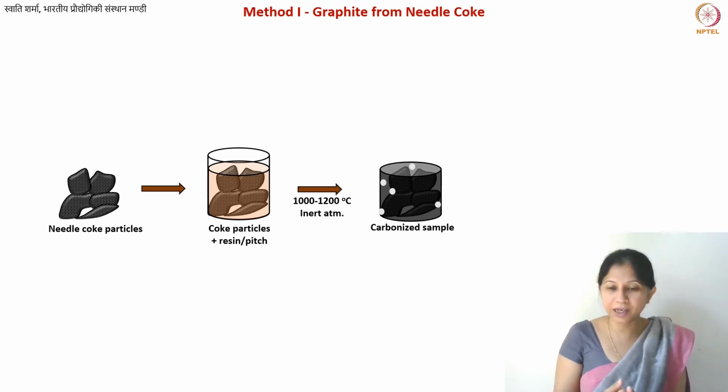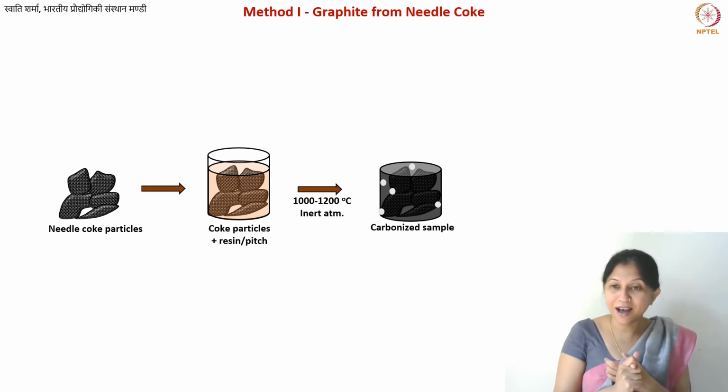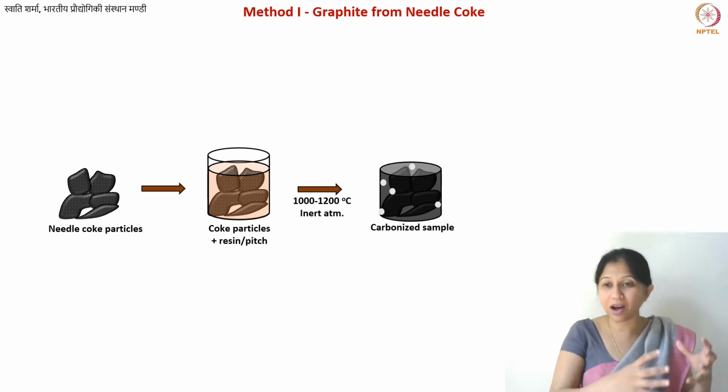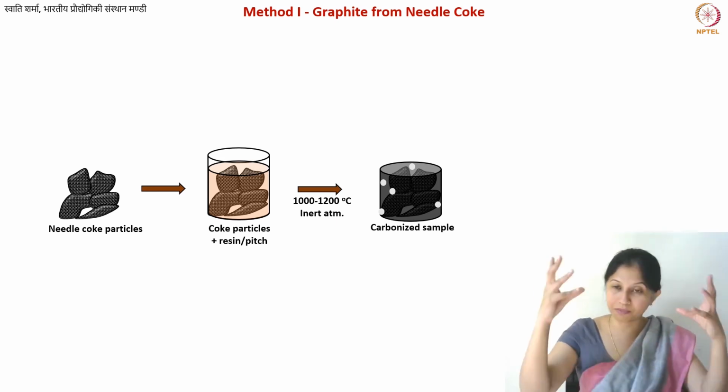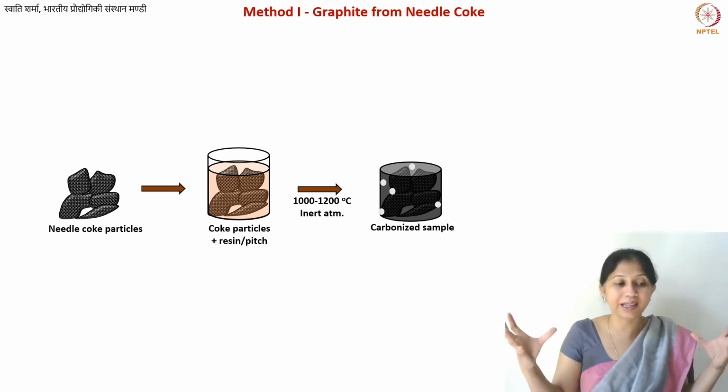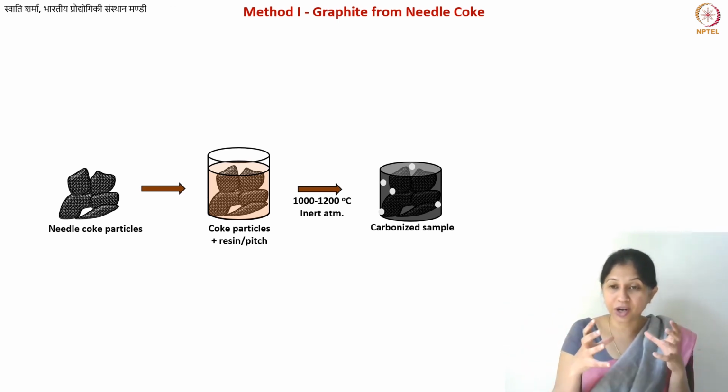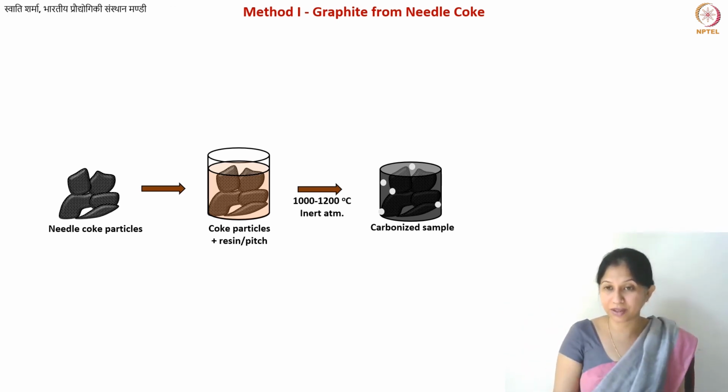However, this carbon material will still have impurities, and what it will also have is pores. Why will you have pores? Because all the non-carbon atoms or whatever, there is some net mass loss from your material, right? So how will that mass be lost? Either the entire thing will shrink, or you will get some porosity.